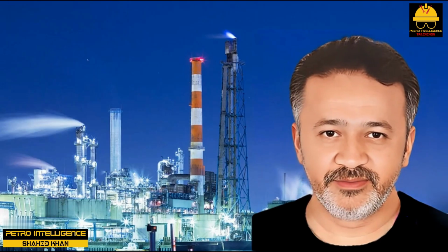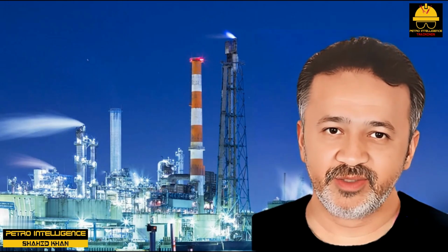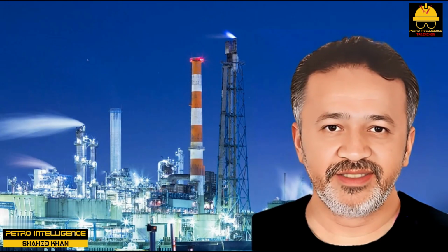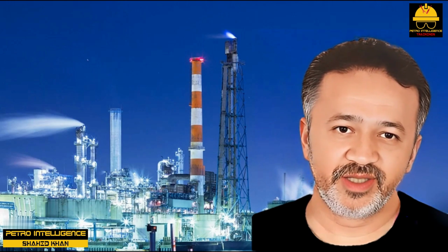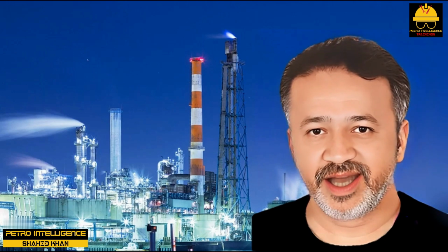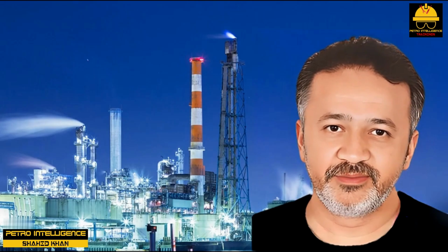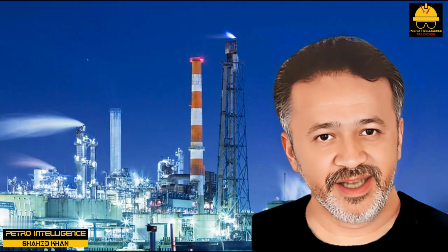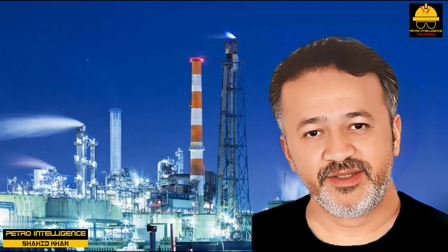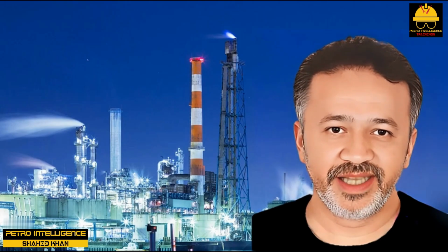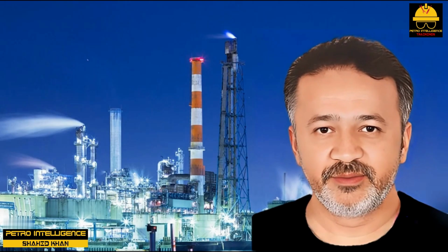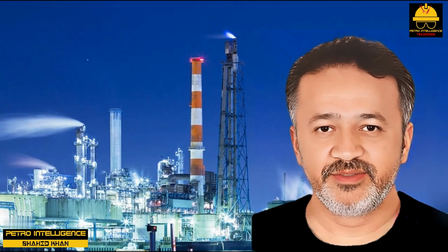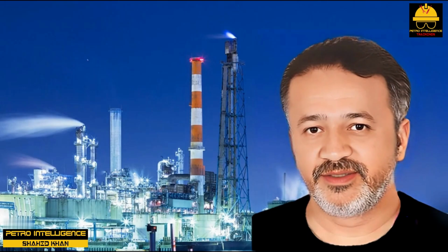Vapor trap. Another way of looking at the receiver vessel is to think of it as a giant steam trap. As long as the liquid level is maintained in the receiver, uncondensed refrigerant vapors cannot escape from the condenser. Let's assume that such vapors did escape from the condenser. If there were no refrigerant receiver vessel, these vapors would blow through the letdown valve. Reducing the pressure of the vapors produces just a tiny bit of refrigeration as compared to vaporization of liquefied refrigerant.